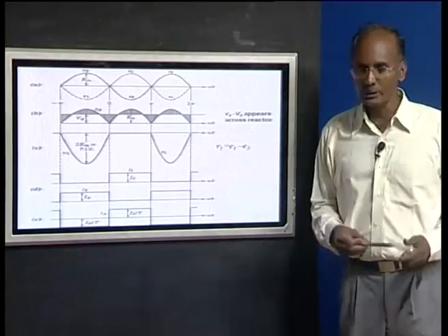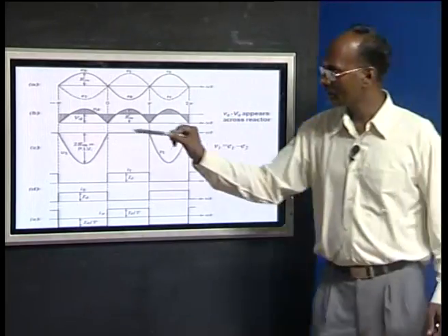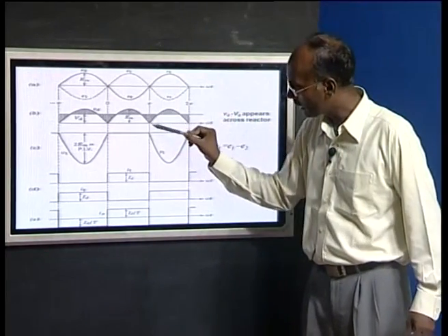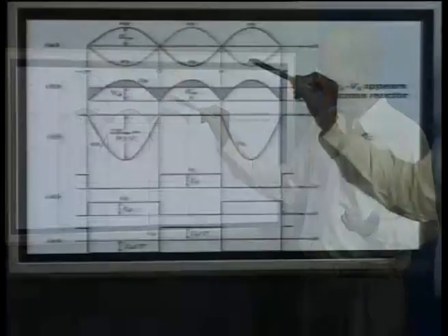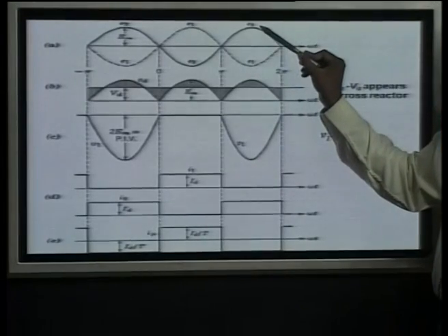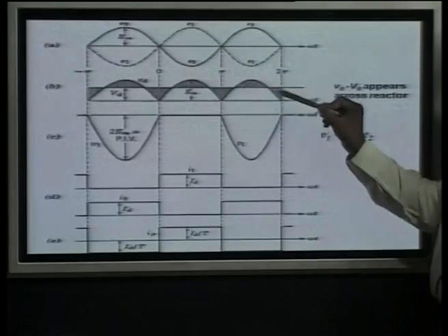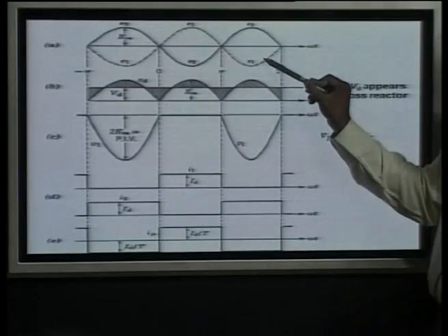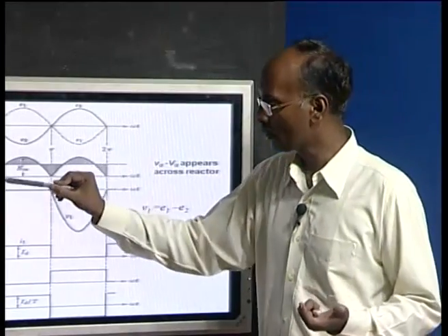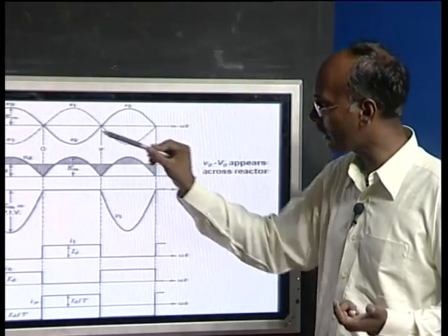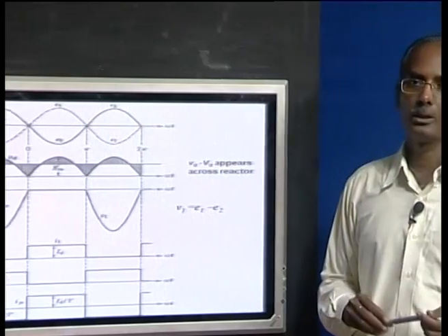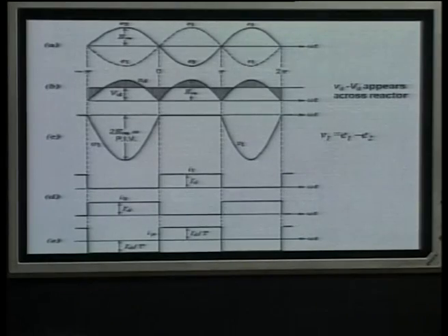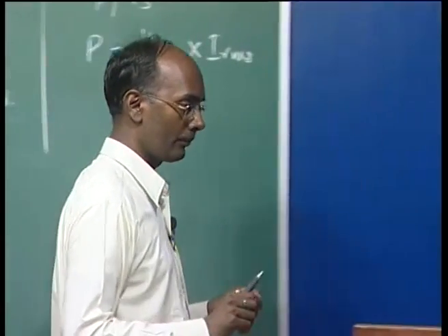For the output voltage in the circuit, when E1 is positive the first valve is conducting, and when E2 is positive the second valve is conducting, and valve 1 will be off. So, in one cycle we get 2 pulses. So, the number of pulses is 2, and we have assumed IDC is constant.